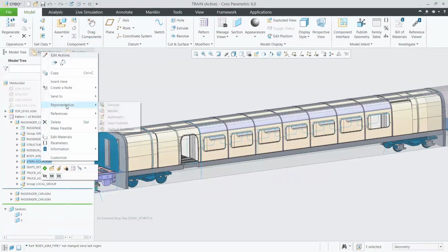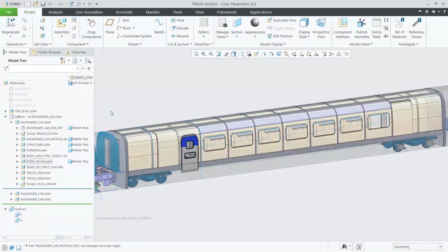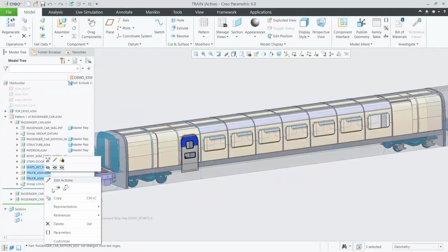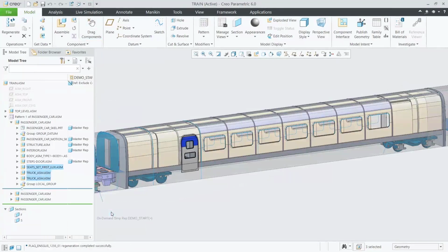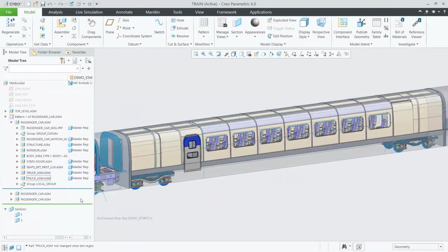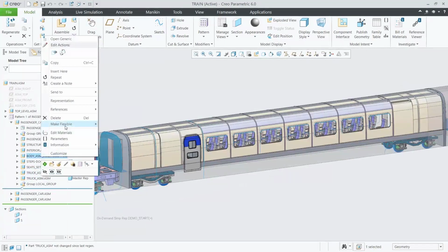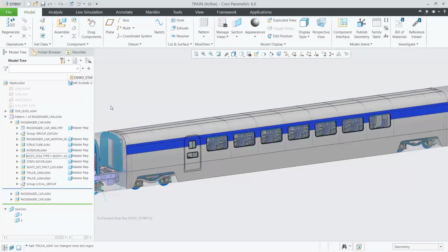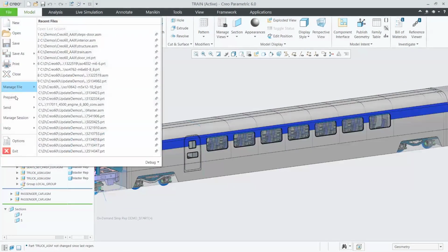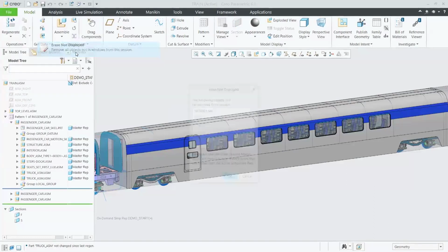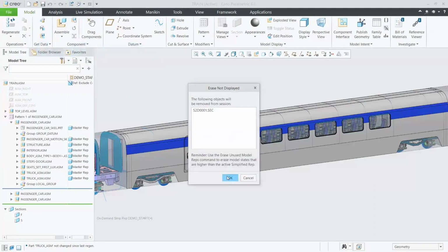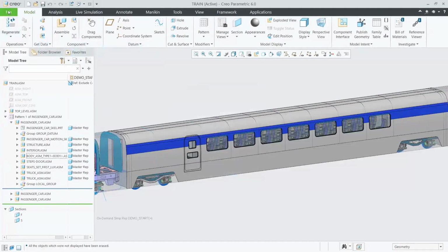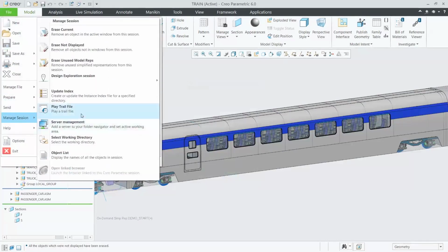Load that up here. And that's really, again, with the advanced assembly extension, what you're doing is setting these different representations, copy geometry to the particular areas that you work from it, and still set up the skeletons to keep control of everything. And that's really what you need to do in order to work with models that are of this complexity. Otherwise, you have too much in front of you. So from this point, now that I have this all set up, and I want to go ahead and make some changes, right? This might be later on where we need to make some changes to some input geometry.